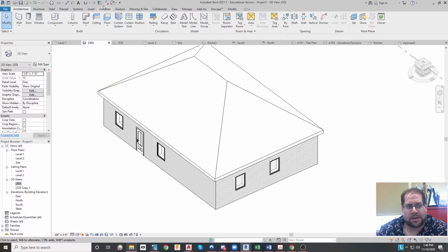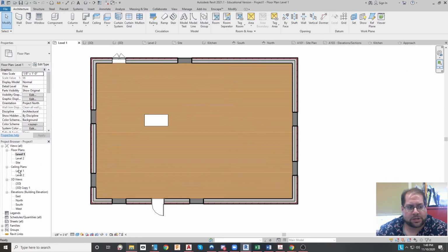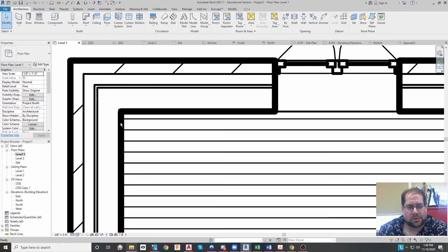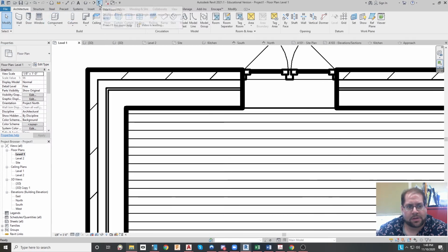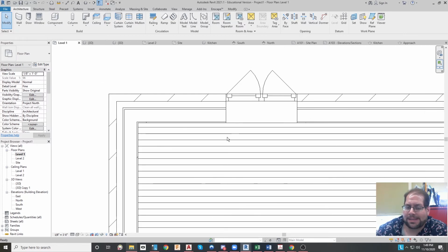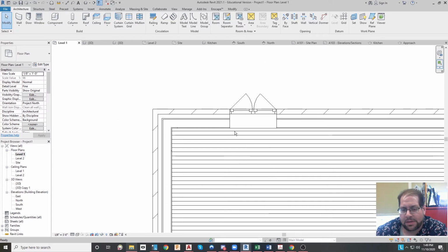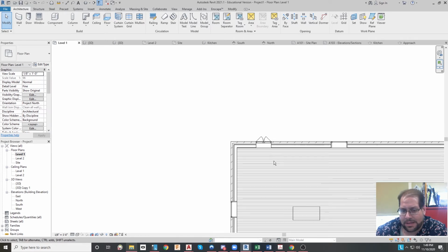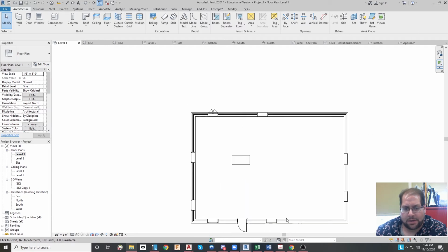If you have thin lines selected, then when you look at the actual walls here, you'll see that certain lines are thicker than others, and it makes things difficult when you're trying to snap onto things. So you click on this thin lines feature, and it hides the actual thickness of the lines, so you can quickly access things, especially again when snapping onto items. It's a very important particular command to be able to access.